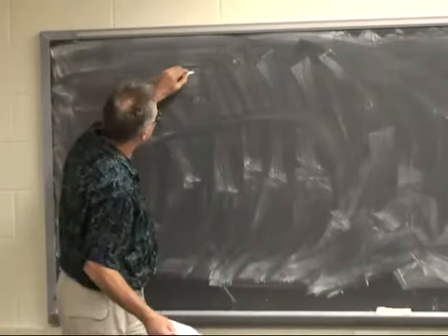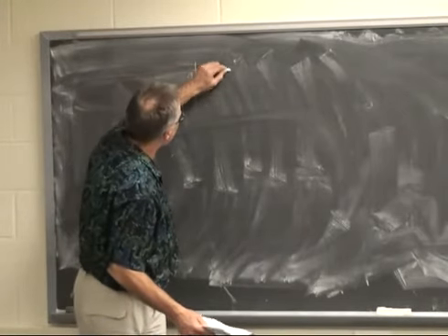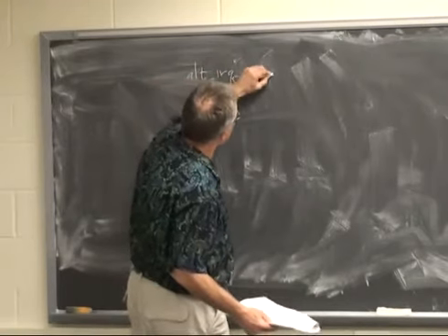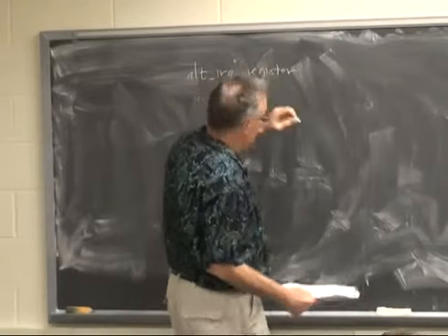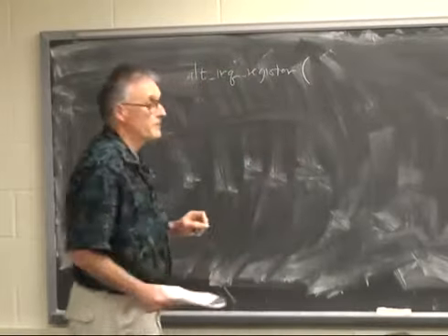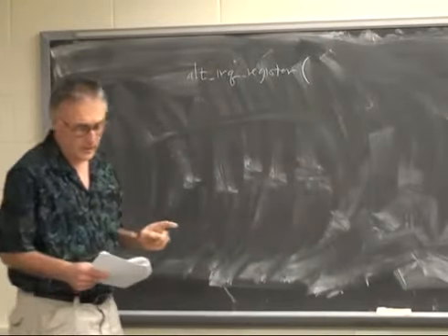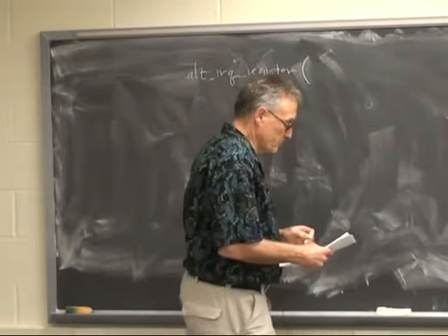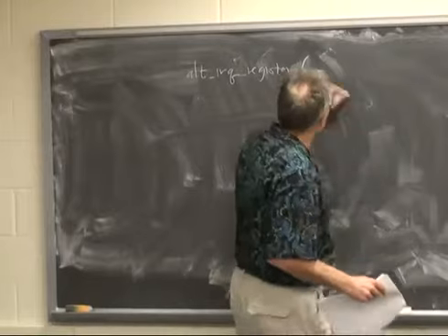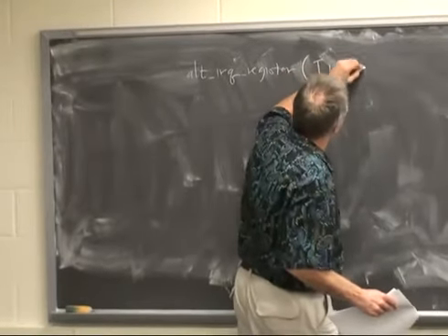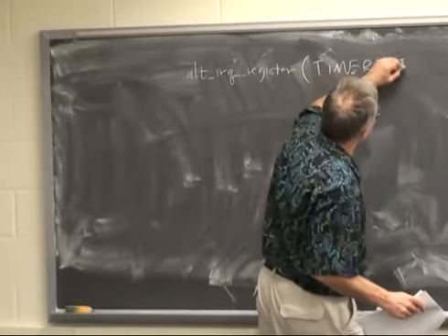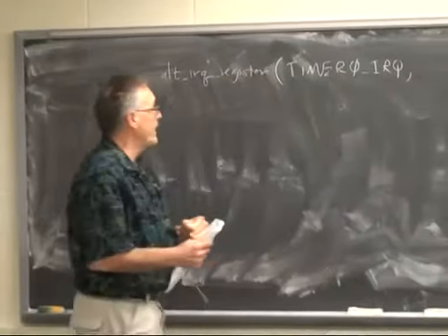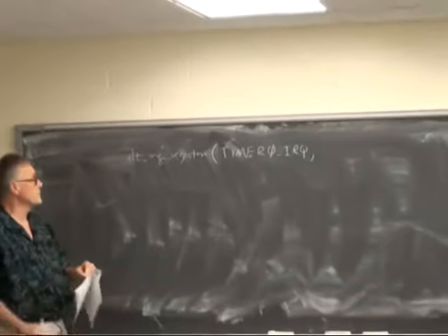So I'll start again with alt_irq_register, which associates the timer 0 IRQ with a given interrupt service routine.